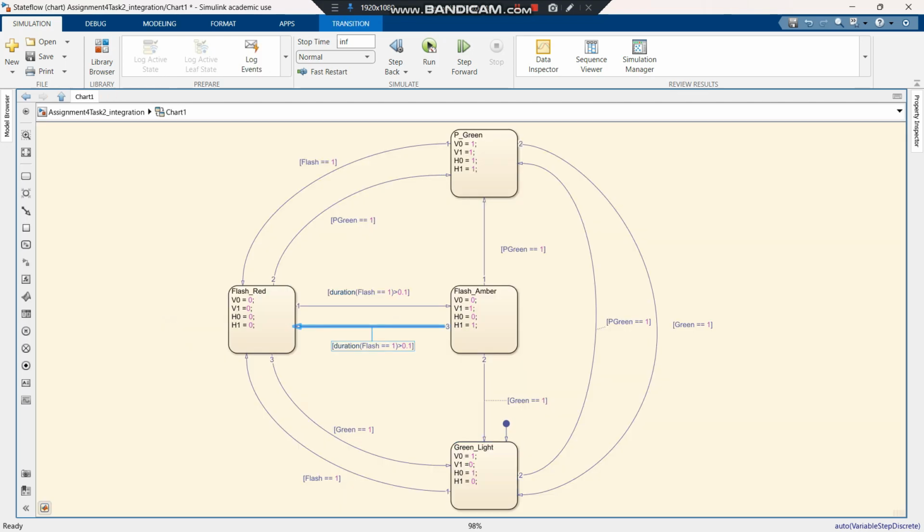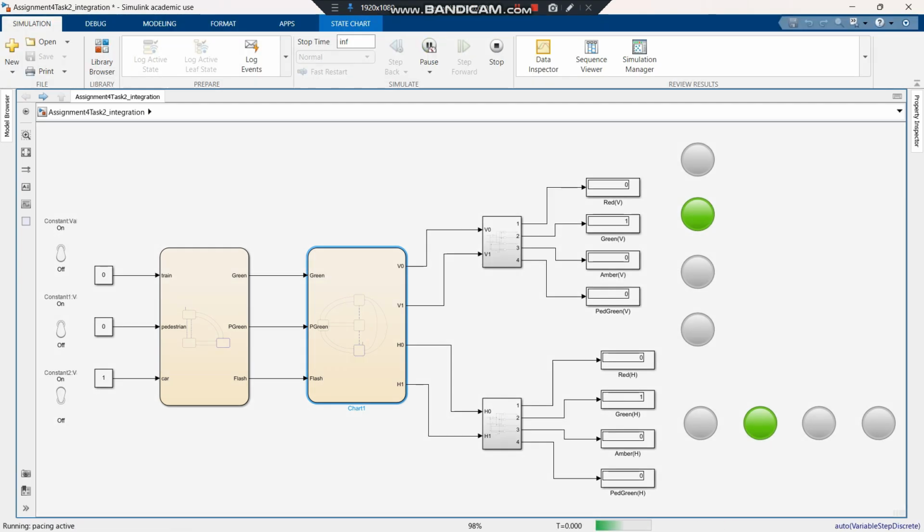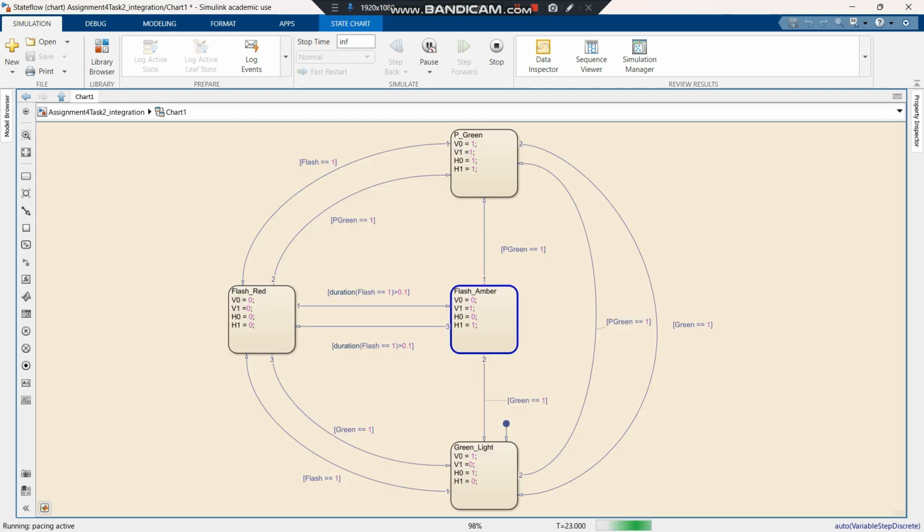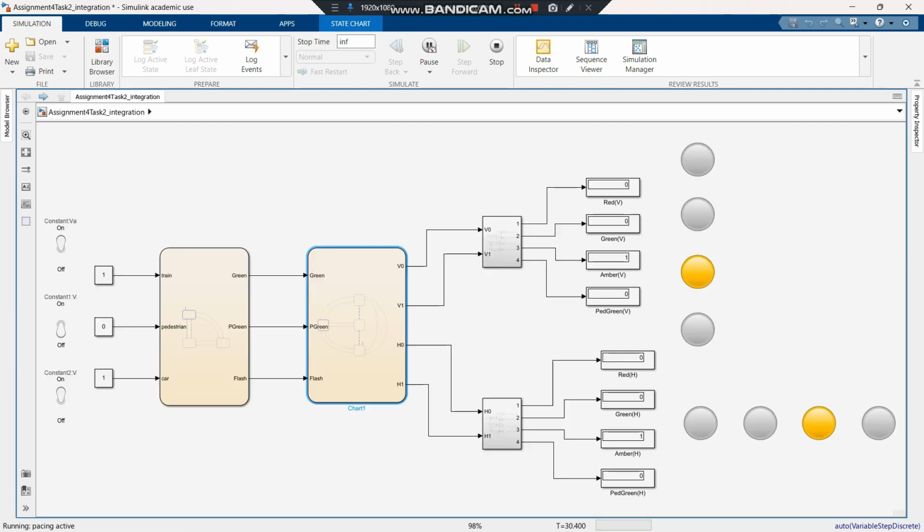So there is also a requirement for us to toggle the red and amber with 10 hertz frequency. To achieve this, I use the formula T equals 1 over F to get 0.1 seconds, so that when I turn on the system and the train button has been activated, it will toggle the red and amber light with 10 hertz frequency. And I have also integrated what I have just explained for my design task one, and this is what I got from my workshop exercise 4, and I have put them all together, and that is all for my design task 2.